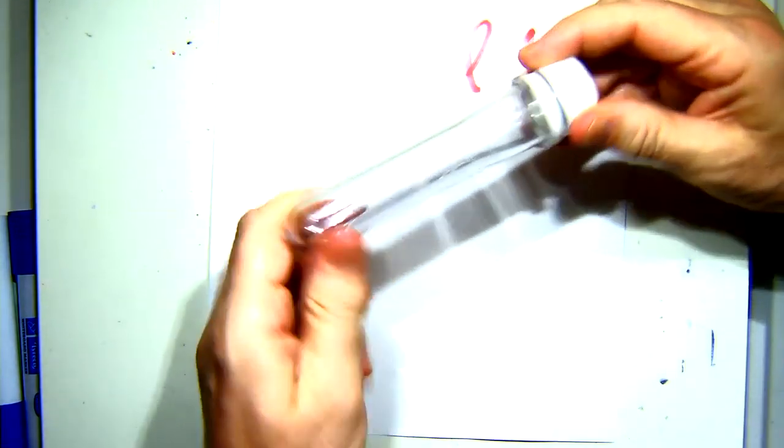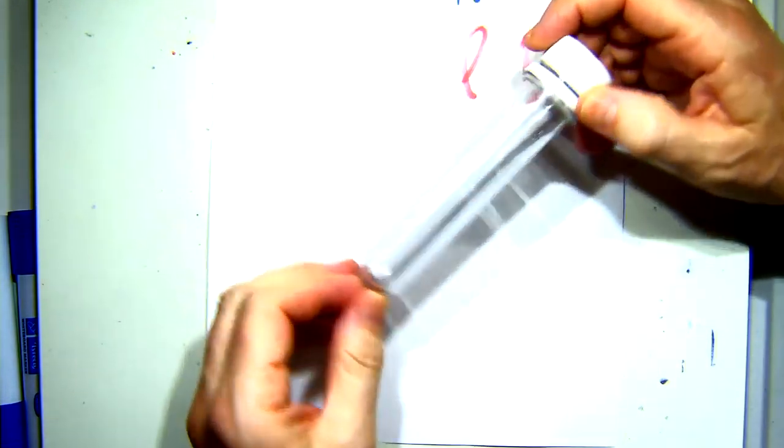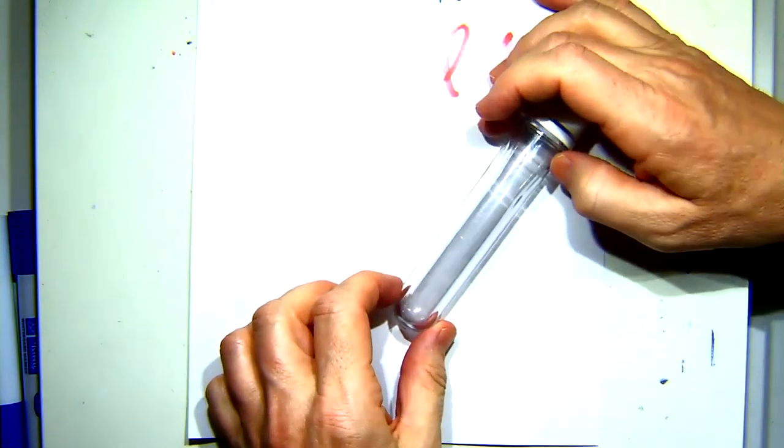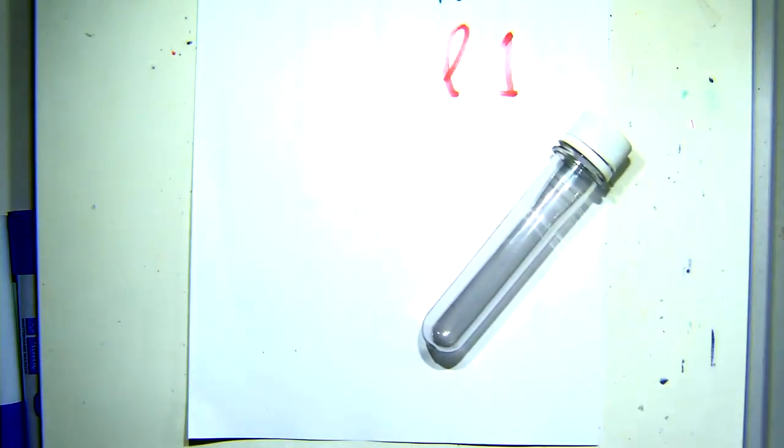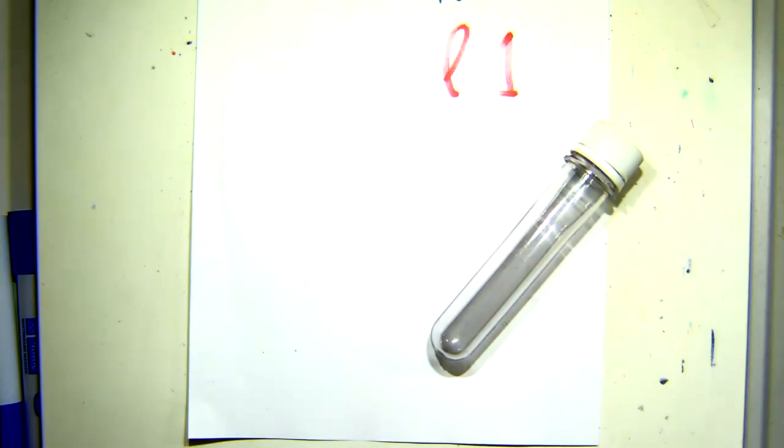It looks a little bit like a vessel you'd find in a laboratory, but it's not. That object is this object up here. It's like a preliminary manufactured component that will later be turned into a final, if you like, carbonated bottle associated with stuff we go and buy at the supermarket. It's called a preform. It's used because it's cheap, simple to manufacture.